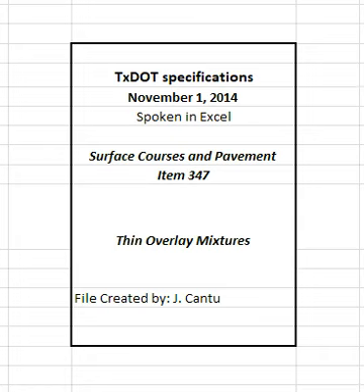4.4.2 Job Mix Formula Approval. The Job Mix Formula, JMF, is the combined aggregate gradation, target laboratory molded density, or end design level, and target asphalt percentage used to establish target values for hot mix production.